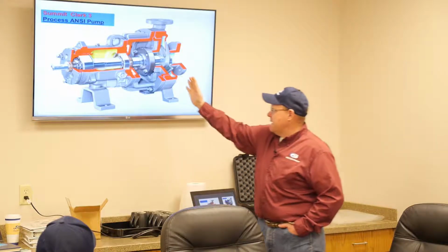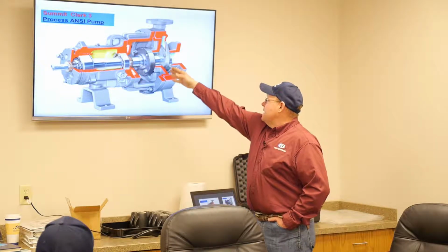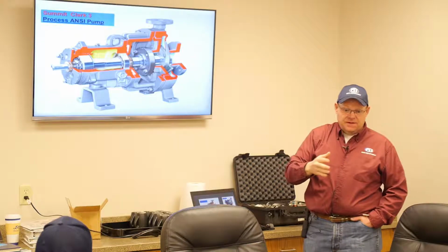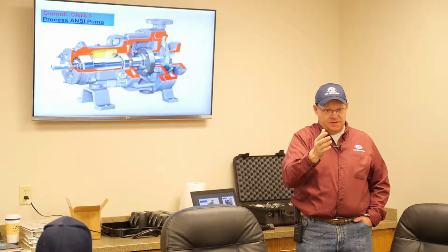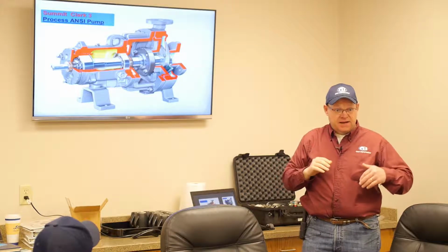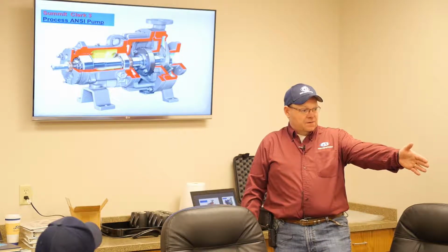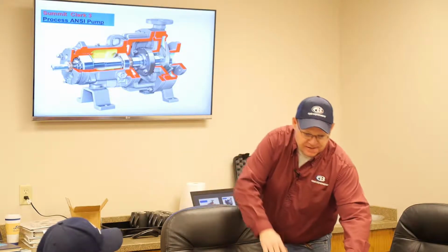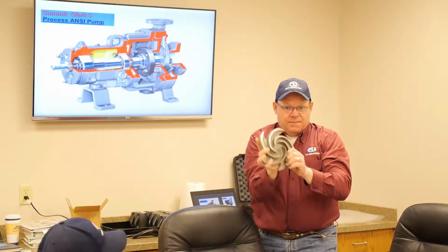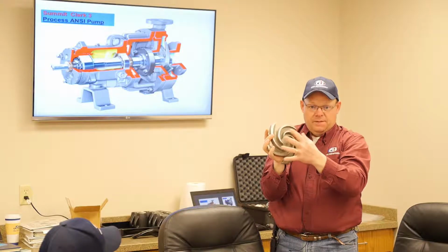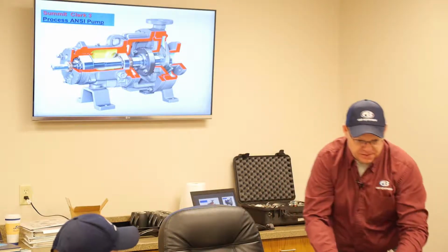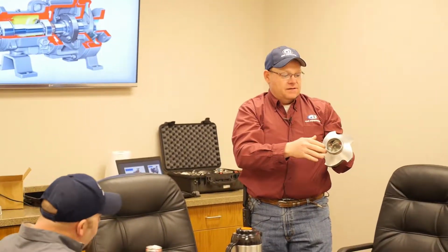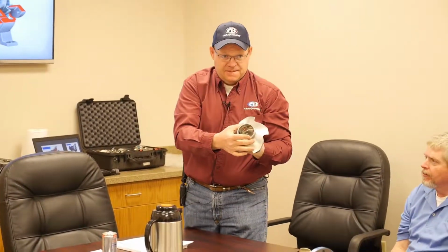Same principle. Bearing frame back here, outboard, inboard, stuffing box, impeller. Obviously everything's the same, except yours is an enclosed, semi-enclosed impeller, reverse vane, also same term. The ones you're more familiar with on the Goulds are going to be a semi-open impeller. The difference is obviously, this is a Goulds impeller. There's no cover on the front, so it's open. We call it open impeller. This has obviously a cover over the front, so we call this a reverse vane or semi-enclosed. Does that make sense so far?